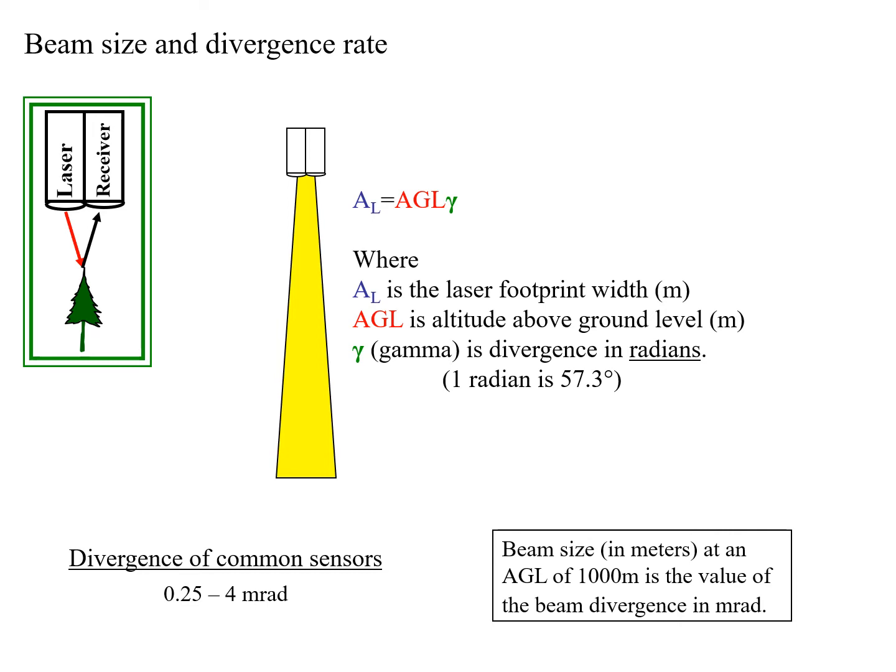So there are ones that go that far, and for that application, you probably want the beam to be the same diameter throughout the line that it's following. However, for LiDAR, you don't want it to be that compact. You want it to be spread out a little bit, both for eye safety and because you want to capture data that's going to be averaged over a larger, what we would say is a larger footprint. The footprint being the intersection of the beam and the ground surface.